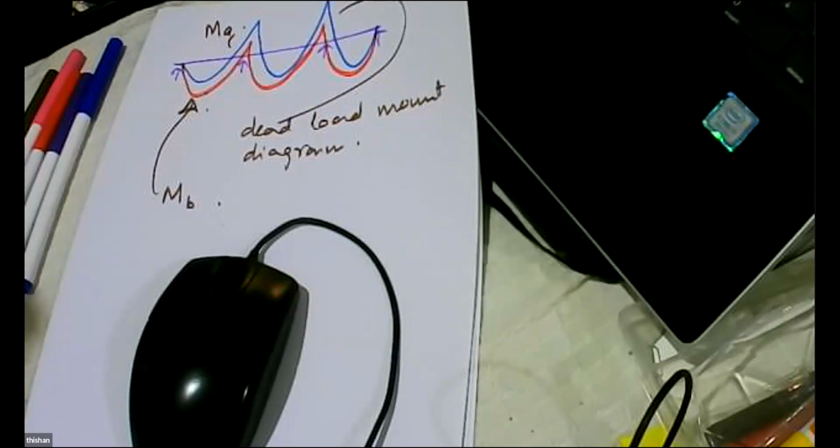We have to look into all these different aspects, and then how to apply the loads that are given in BS 5400 part 2, or else we have to see how the Eurocode based loads can be applied onto a bridge, so that we can find the bending moment diagram that I have used.